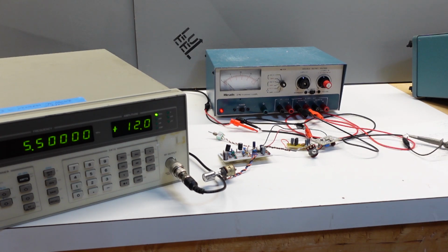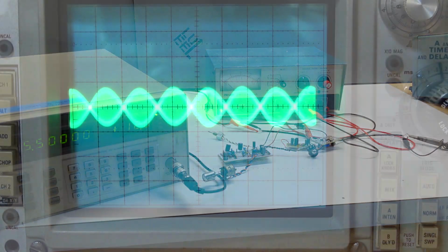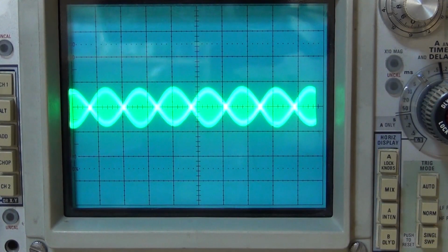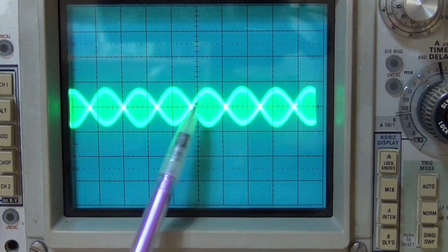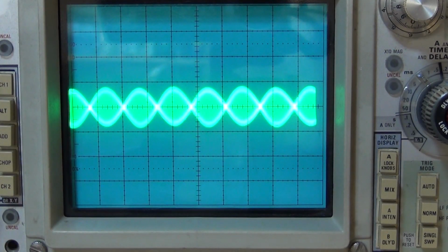So looking at the RF output, what I've done is reconfigured the scope and the probe yet again. I switched it back to x10 mode. I set the vertical scale to 5 millivolts, and by the way, that is the highest resolution voltage you can get on a 465. It doesn't go any lower than 5 millivolts. And lo and behold, on the screen we can see the characteristic signal of either AM modulation or double sideband. You really can't tell with a scope because if I remember my theory right, the only difference is the phase reversals at each of the zero crossings, and of course you're not going to see that on a scope.